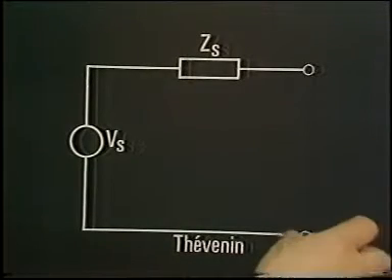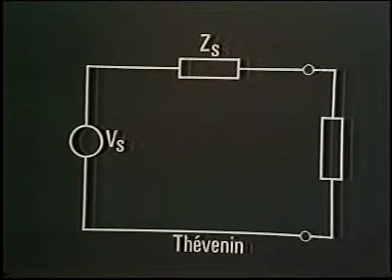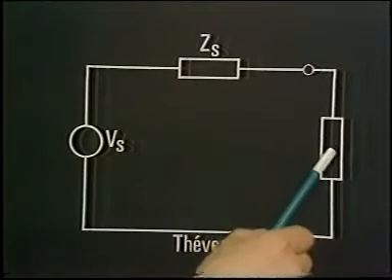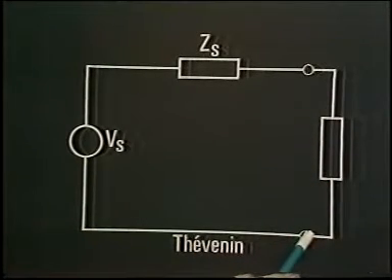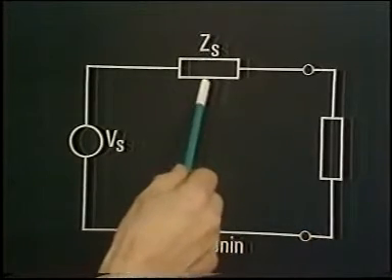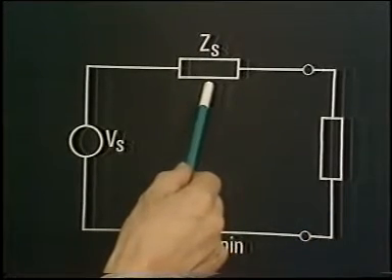Now, in general, it's not so easy to do that because it may not be possible to turn off the internal generator. So the other way is the method that you used in the experimental work for an earlier part of the course, where you measured the equivalent circuit of the sine wave generator and the oscilloscope. The technique there is to load up the circuit with a load impedance. You used a load resistor, and that enabled you, by measuring the voltage across the output terminals and the load current, to measure the equivalent series resistance. Well, now, let me come back to our magnetic pickup again.